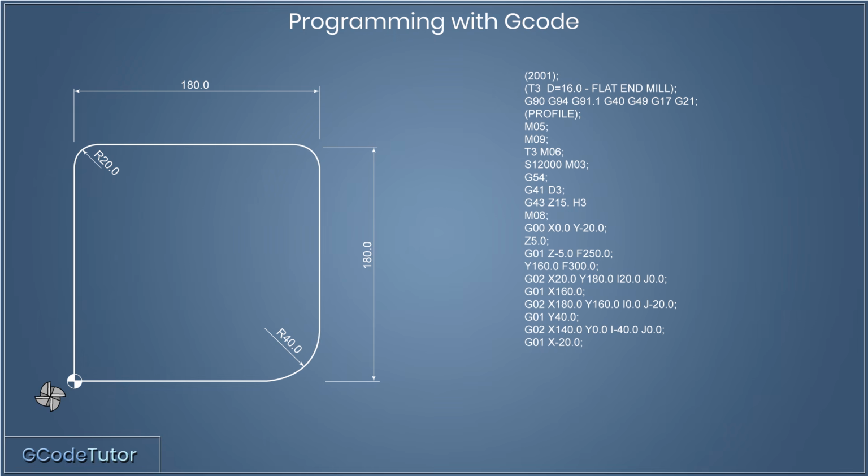Now all that's left to do is to move the cutter back to its start position and a safe place where we can lift it from the material. So G01 X-20 will bring the cutter 20 millimeters to the left of our datum position. And that brings the cutter over to where it's shown on this drawing. So now we can lift the cutter away from the component and it won't be touching an edge of the component that we wish to keep nice and clean.